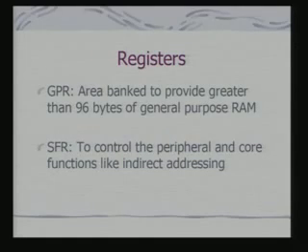Again, I am talking about mid-range processors, and depending on which microcontroller you choose, this value would change. And the SFR, or special purpose register, is used to control the peripheral and core functions like indirect addressing. Peripheral control means that if I have to program the peripherals, set some bits on the peripherals, then we shall be using these special function registers.